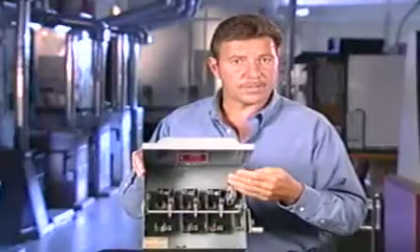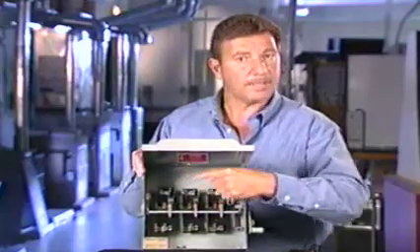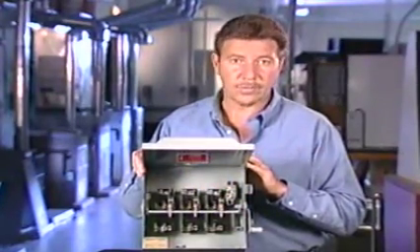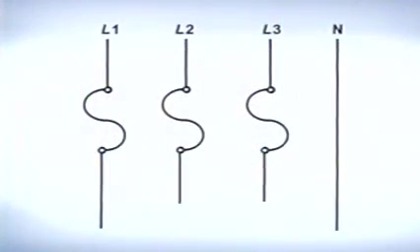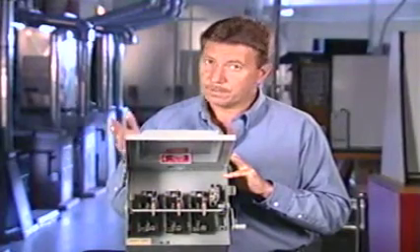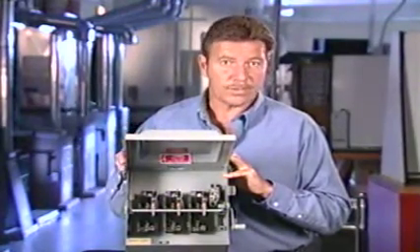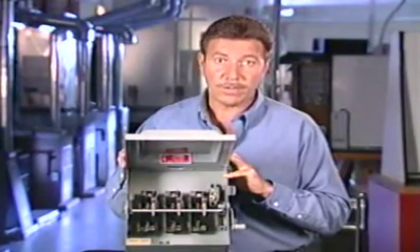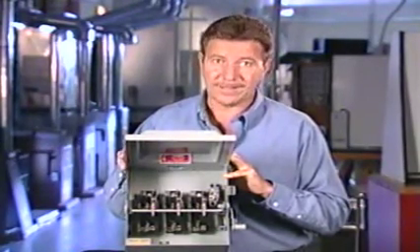Three-phase electrical services supply three hot legs of power to satisfy the needs of many commercial and industrial applications. Three-phase power is configured with three fused hot legs and one ground wire. It's essential for the technician to understand three-phase power supplies because of their versatility and the different voltages that these supplies can provide. Three-phase power can be configured as either a Y or delta system.